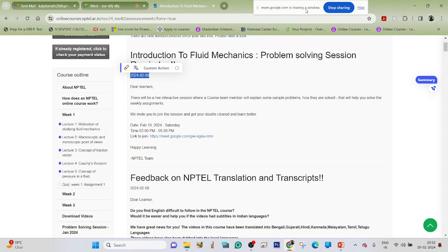If this is a body, and pressure here is p and this is dx, then at the other point the pressure will be p plus del p by del x dx, right? Yes, ma'am. So there is a change in pressure in a fluid element. Even if it is static or moving, there will be a change in pressure. That's why in a pipe, fluid flows.